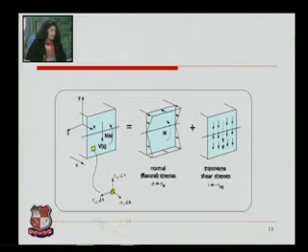So along the X axis we are showing the bending stress along the X direction multiplied by dA, and along the Y direction tau xy. That is, if the bending stress is along the X direction, then there will be transverse stress in the vertical direction, that is tau xy, and in the Z direction. So this diagram shows the development of transverse shear stresses as well as normal stresses.